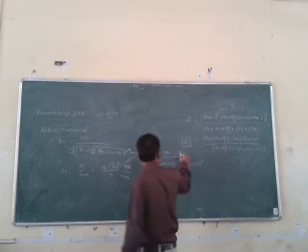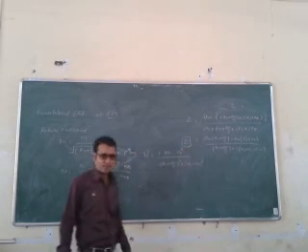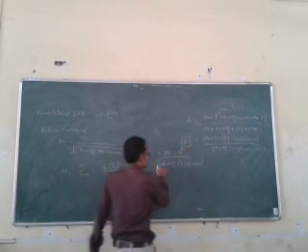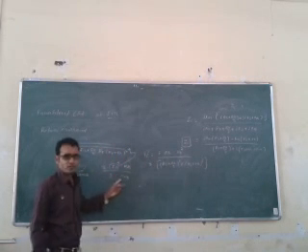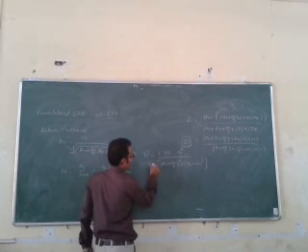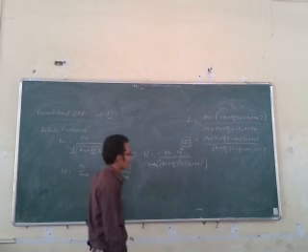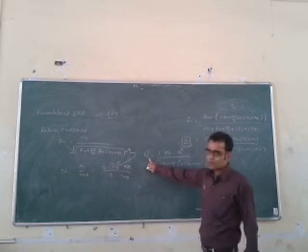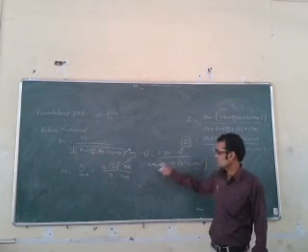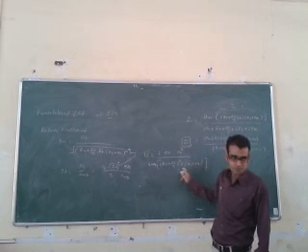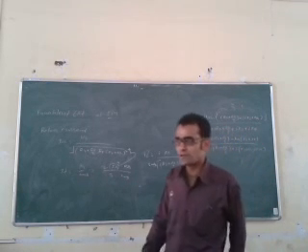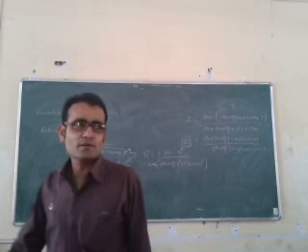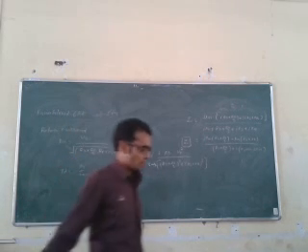There is a root, but here it is a square. The root will go away. Here instead of VS, VS square upon this. Divide by the synchronous speed marking, RR by S into omega S, S omega. What is developed torque? That is 3 times RR into VS square upon S omega S in bracket this bracket. This is what? The actual torque developed inside the rotor.